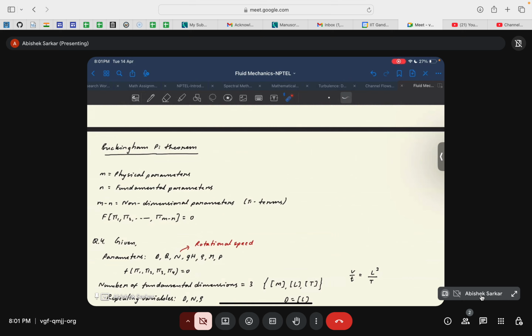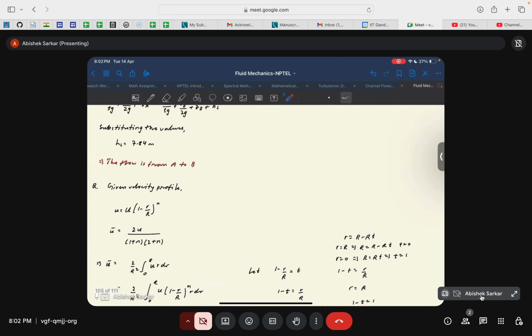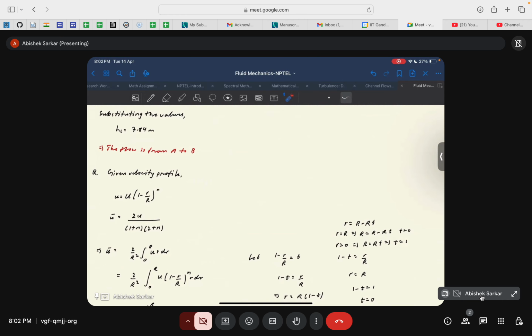If some regions are not able to have the exact velocity conditions that we have here, rather than prescribing the velocity, we can prescribe the Reynolds number, and they can tweak parameters such as the viscosity or the length along which they measure the Reynolds number to match ours, rather than explicitly matching the velocity conditions. That's how the Buckingham pi theorem turned out to be important, and we then took examples to understand its application.